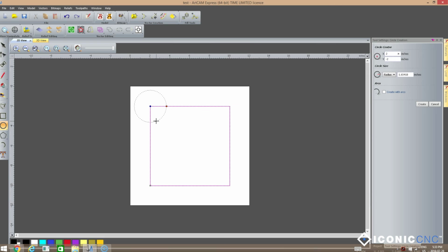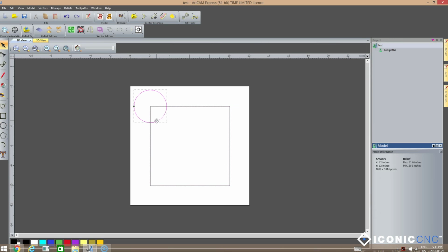And when I'm done, I'm very simply just going to right mouse click. That right mouse click is a very powerful function in ArtCAM, because it not only completes the operation, but if you look over on the right, it actually closed the pane or the window that we were working in as well. So I'm ready to move on to the next segment of my project.